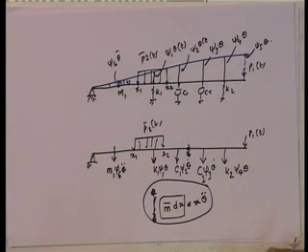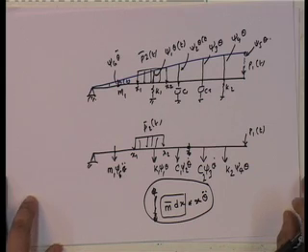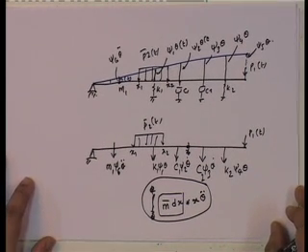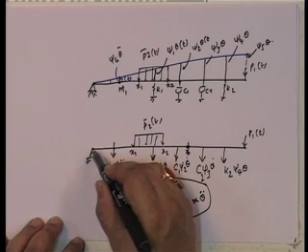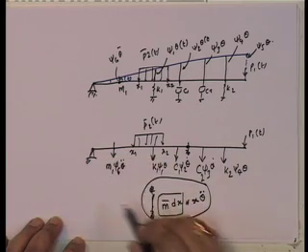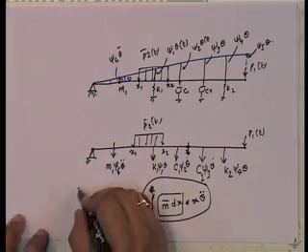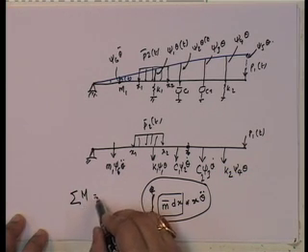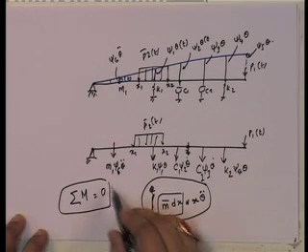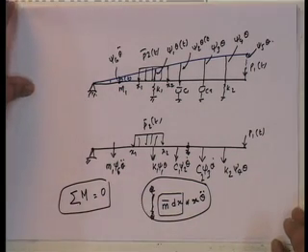So, now these are the only forces that are acting on the structure. Once I have all the forces acting on the structure, what do I do? Well, I have to write down an equation of equilibrium. And what is the easiest equation of equilibrium in this particular case? The easiest equilibrium equation is that since this is a pin here, the moment about this point has to be equal to 0. So, at an instant of time t, the moment has to be equal to 0 instantaneously. Remember that we are taking it at an instant of time t.